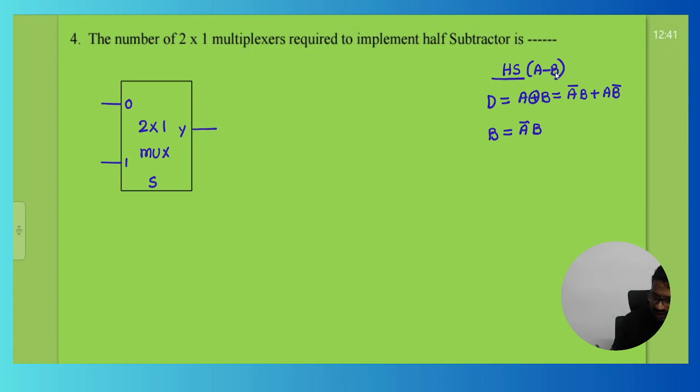For this, first I am taking the terminals. Terminals, you tell me now. I am taking this as A, we have connected. This I connected to 0. So then what will I get, tell me now here? So what will come as this output? Tell me now here. Here I am giving A. So what will I get as the expression here? Output is A bar into B. So that is the borrow. Next, what else do we require, tell me now here?